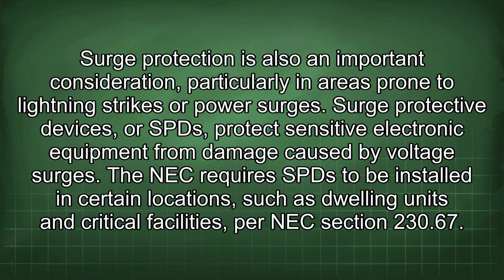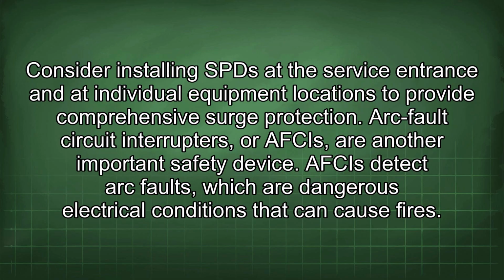Surge protection is also an important consideration, particularly in areas prone to lightning strikes or power surges. Surge protective devices, or SPDs, protect sensitive electronic equipment from damage caused by voltage surges. The NEC requires SPDs to be installed in certain locations, such as dwelling units and critical facilities, per NEC section 230.67. Consider installing SPDs at the service entrance and at individual equipment locations to provide comprehensive surge protection.